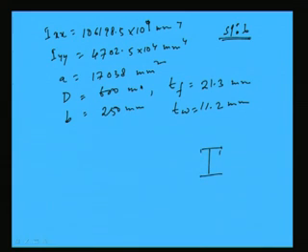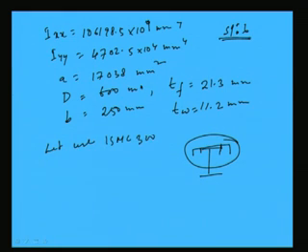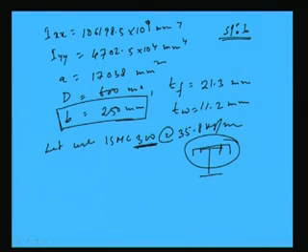Also, we have to provide a channel, and as we told earlier, if the I section has some B width, then the channel depth has to be a little higher, around 50 millimeter higher. So, considering this, let us use ISMC 300, say at 35.8 kg per meter. As the flange width of the I section is 250 mm, we should choose a channel section of at least 300 mm, because the channel depth has to be at least 50 mm higher than the flange width of the I section, right. So, this is 250 and this is 300. So, 50 mm higher we are making.